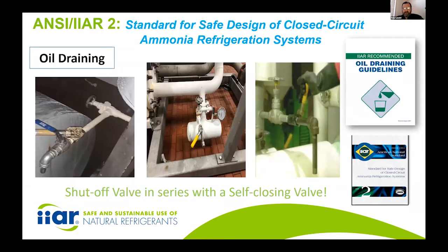Also, there's oil draining where you have a shut-off valve in series with a self-closing valve. Here are some examples. You see the first valve coming out from under the equipment on each, and then you see a spring-loaded yellow handle valve that will close itself. Those are key items to have in series for when you do your oil draining.